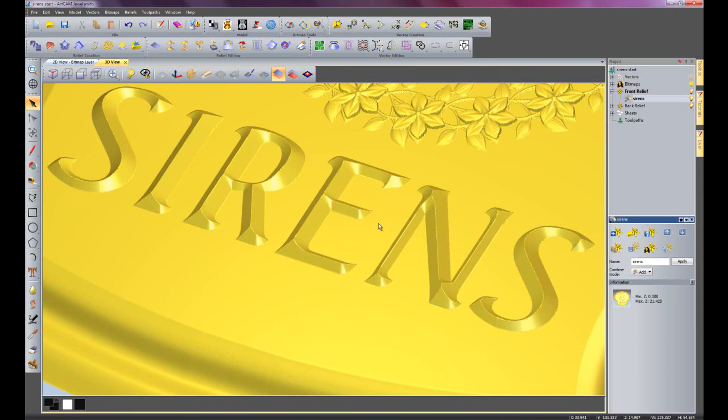There are problems with the letters, especially for instance the R and the E in the centre. You can see the lower portion of the E in the center here is trying to blend up into the higher portion on the left of the E. And what it's doing, it's just creating a blend from the top going up, and it's creating this nasty dimple effect on the sidewall of the E here. Also giving me the same effect on the R.